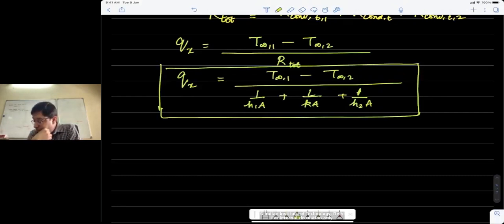Think about this. In that case, if we look at any cross section, the heat flux will not be constant throughout the material. In the transient case, it may not be constant. Can we say that in the transient state the resistance that we got here will not be the same? No, the resistances will be the same, that is not going to change. But in the transient cases, the temperatures will not be the same, because heat could actually get stored.